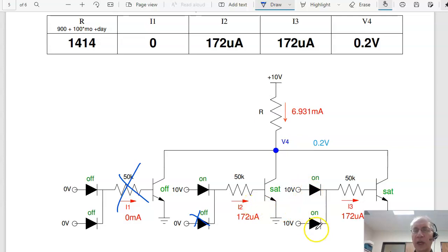And here I've got 2. I'm not really sure which one's turned on. They actually won't both be turned on because if this is just a hair larger than 0.7 volts to turn on voltage, then the bottom one turns on. One of these will have a slightly lower turn on voltage, and that one wins. From our standpoint, it really makes no difference. The net result is this is 9.3 volts, 0.7 volts, 10 minus 1.4 over 50K is the current.